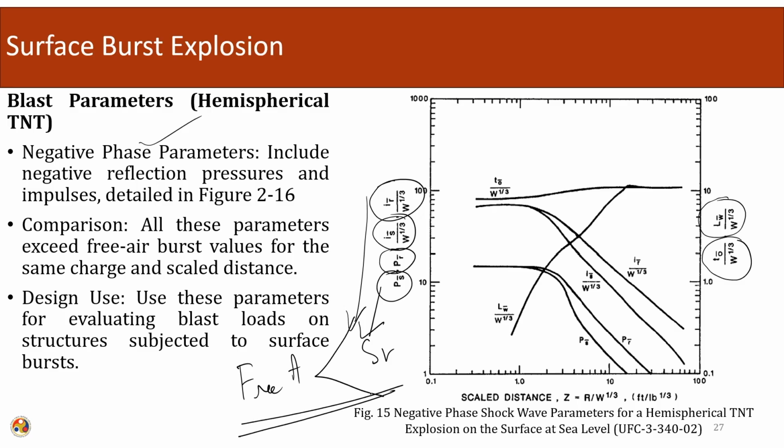Similarly, these quantities can be used for evaluating blast load on structures subjected to surface burst. In the same way in which we have used the air burst quantities, we can use the surface burst quantities also to design for the blast loading. Again it overestimates the parameters, so we will always have an overestimated design on the right hand side. So our design will be safer, or it will have more reliability.